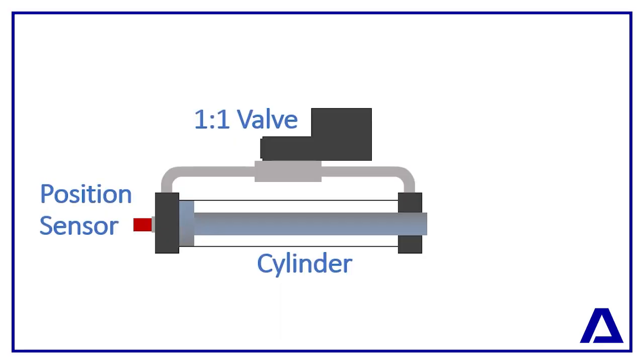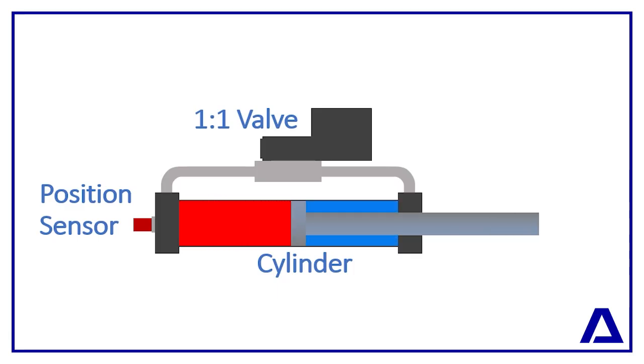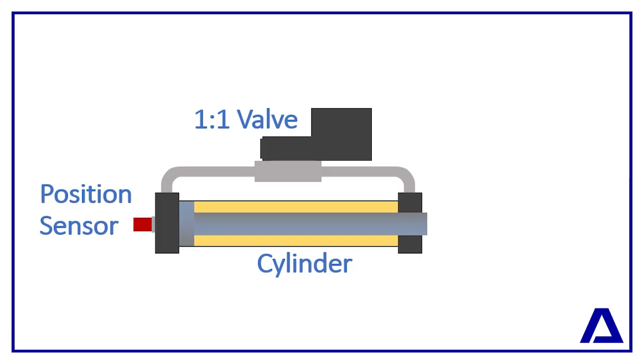In a servo-hydraulic system with a constant supply pressure and a one-to-one valve, a single rod cylinder extends faster than it retracts. We will present the formulas for the velocity of a cylinder in both directions, then explain with detailed algebra how these were derived.